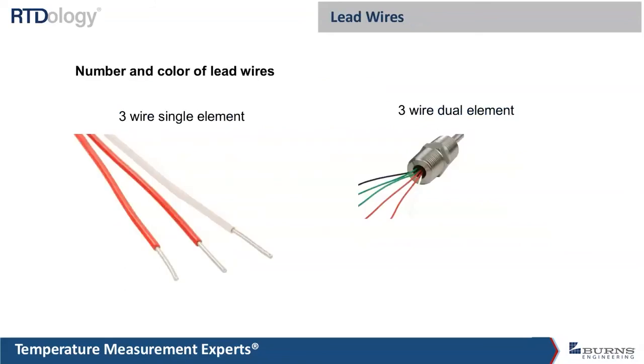First off, one of the first things to look at here would be the number and color of lead wires. Each manufacturer will have color codes. We typically use red and white and black and green, and a typical dual element like shown here is going to have 6 leads, and so one of those sensing elements would be the red and white leads, and the other one would be the black and the green. Here is just an example of a 3-wire single element. If it were a 4-wire system, it would have another white wire here, so it would be 2 whites and 2 reds.